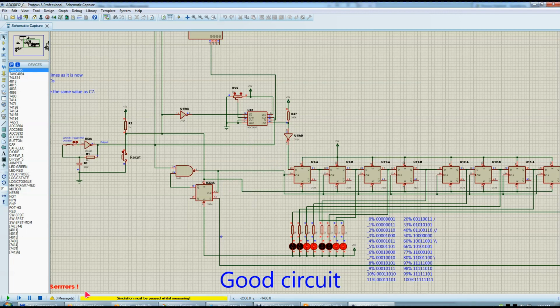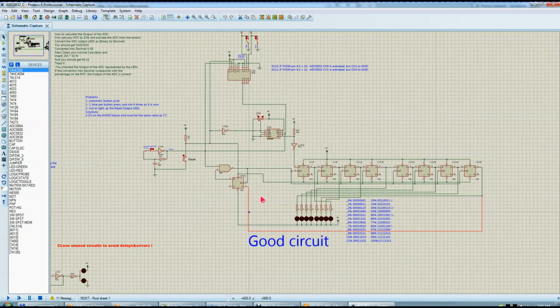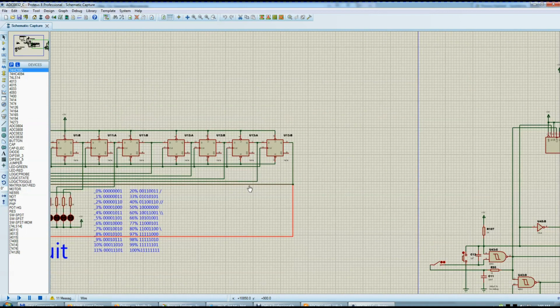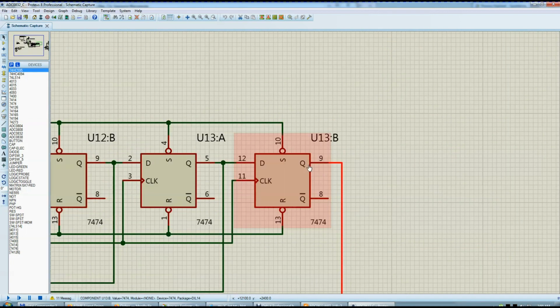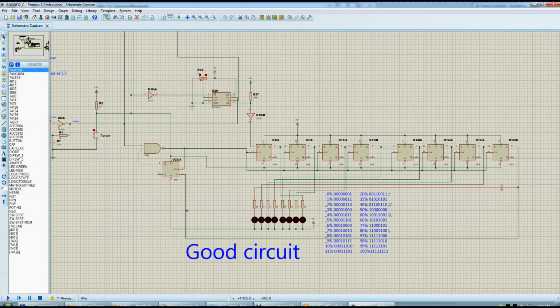And this is getting the signal. Actually, you can see the reset signal is coming from this line now. When I'm clicking this reset button here, it's resetting all these flip-flops. This flip-flop is reset, and all these reset pins of the flip-flops are reset. So the entire driver is reset when I'm clicking this button here. And this line is coming from the last bit. You see, this is the last bit from the output of the last flip-flop, which is this LED here.